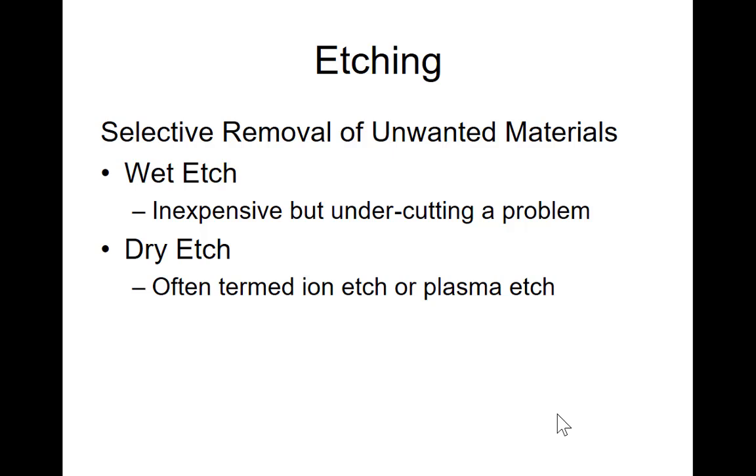In wet etching, you put many wafers vertically in a boat, and you drop the whole boat into an acid water channel, and it flows along the channel for an hour, maybe 2 hours. Then at the other end, you take it all out and put it in deionized water to clean it. That's how you do wet etching.